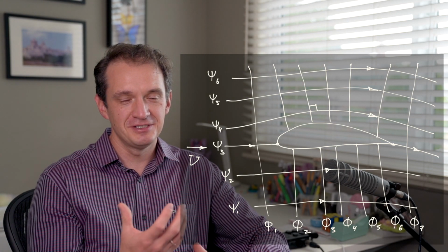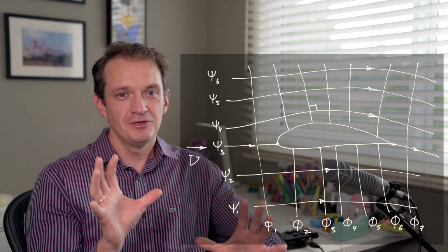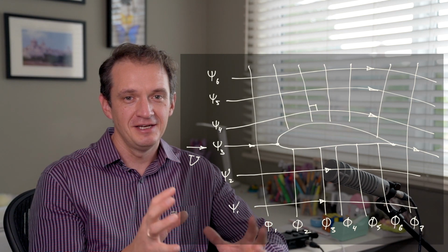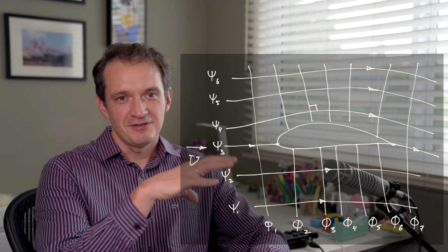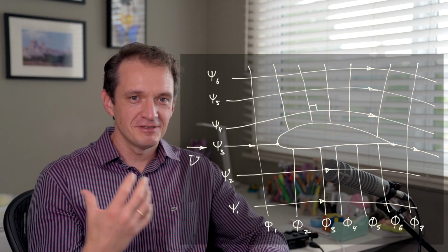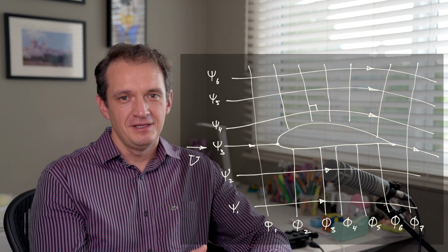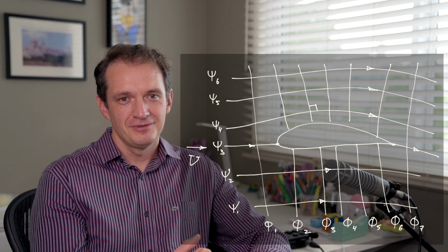Find a potential and the stream function, even if we know that this is not really representative of the physical situation at hand. We could use the flow net that the potential solution gives us as the grid for solution of the actual problem, a more high fidelity CFD simulation.